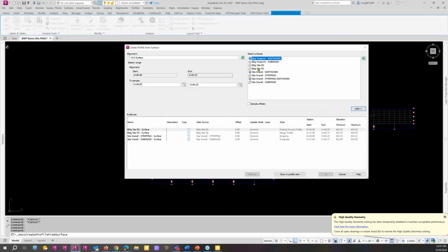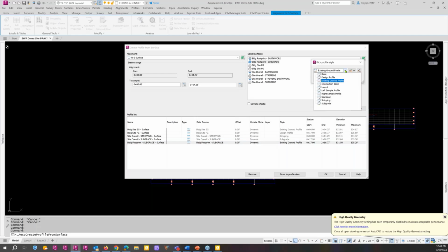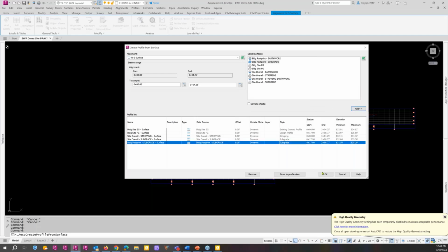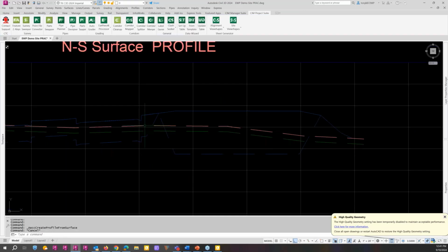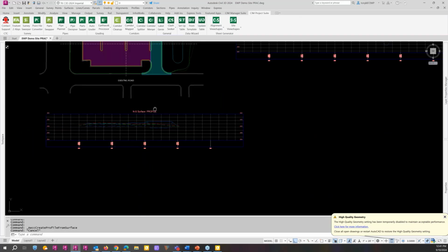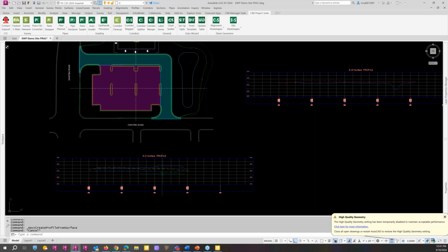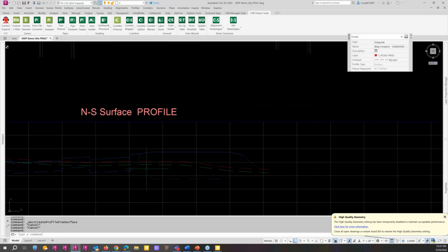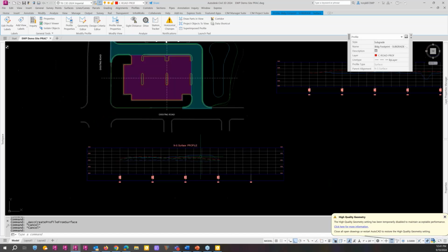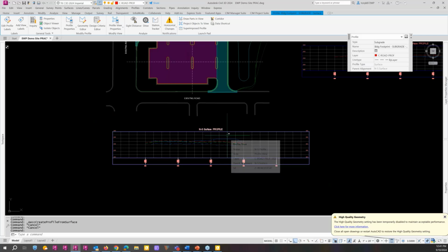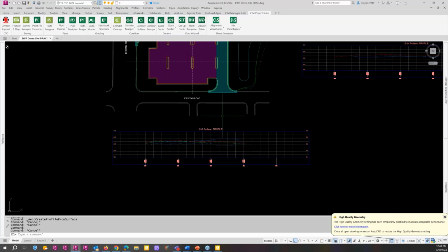So if I add my building footprint subgrade, and I'll also call that subgrade, say OK. And now we can see it comes out to where our other region ended on our heavy pavement out there. Then it picks up for our building footprint. A nice way to calculate some footing grading for a footprint like that. Okay, so now that's all I had to show you.